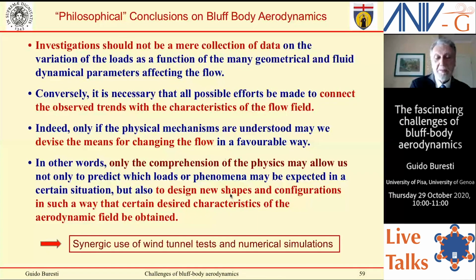Then even the worst code for a flow simulation will give you vortex shedding. Perhaps it will be the wrong vortex shedding, with wrong strength of the vortices, distances, Strouhal number, and loads. But the fact that the vortex shedding is there, you will realize that that phenomenon is there, and perhaps you couldn't understand that from the wind tunnel.